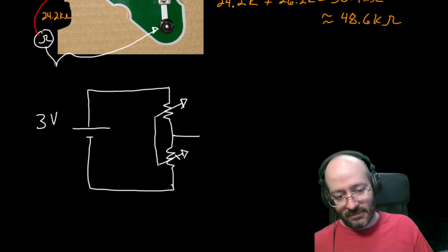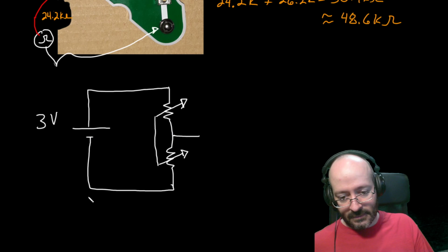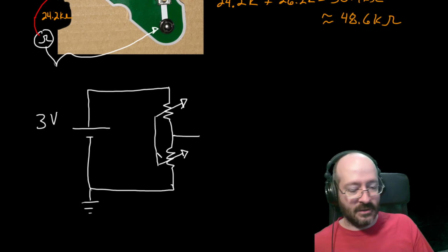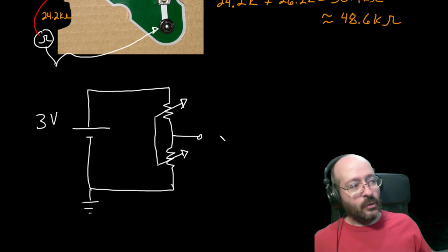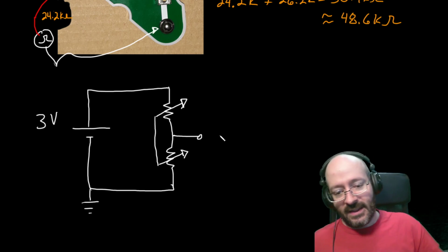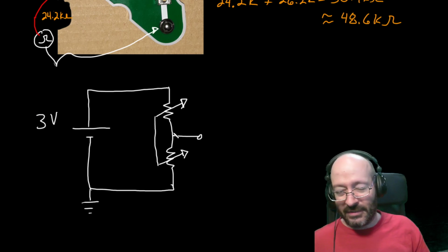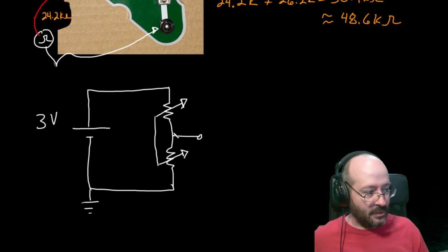And as it's connected all the way down to the bottom, let's call this ground, it's going to be connected to 0 directly. Okay. So we can make this voltage divider, and we can take our 3 volts, and with a couple resistors in the form of a potentiometer, we can make that vary.